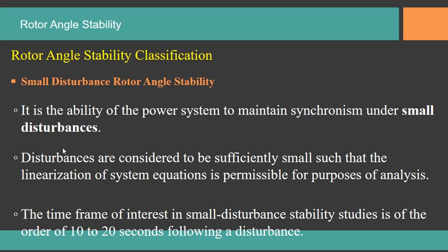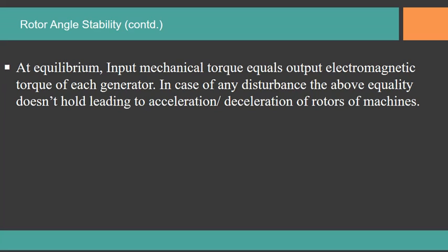The basic phenomenon associated with rotor angle stability is the imbalance between the accelerating and decelerating generator torque, and there is a temporary surplus energy stored in the rotating machines. The capture range of synchronous torque is limited by pull-out torque or synchronizing power. If the limit is exceeded, stability or synchronized operation may be lost.